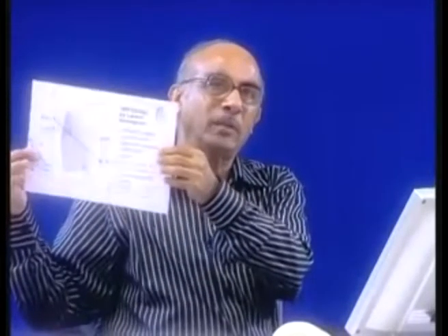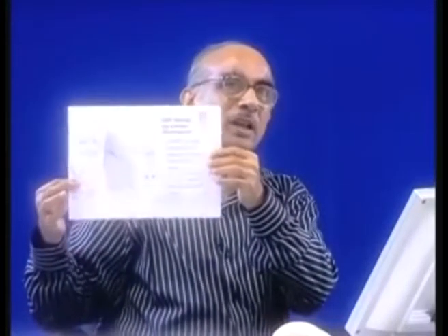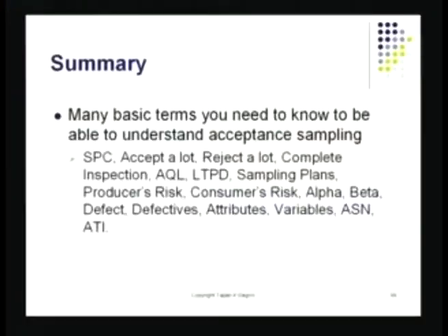You've just got a window open for you. Now this window of sampling has been opened for you. What you have to do is get deeper into this. Pick up the basics you get from these lectures, then get in there and see, do I understand it all? Can I apply it? Can I design a sampling plan? For example, you must try, I'm certainly not kidding, to see if, given AQL, RQL and basically your alpha, beta, can I come up with my n and c? Can I come up with that sort of plan? That would be a big booster as far as your confidence goes.